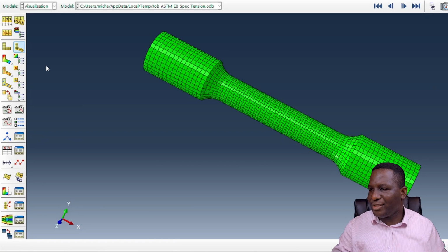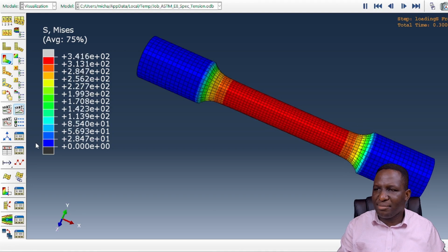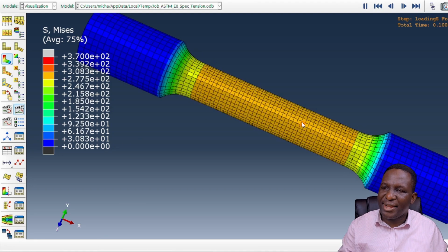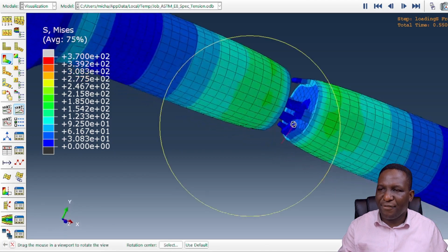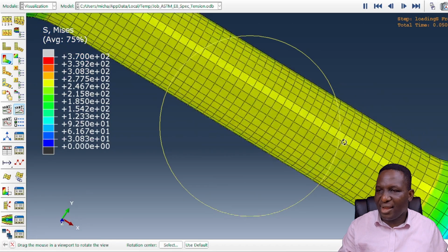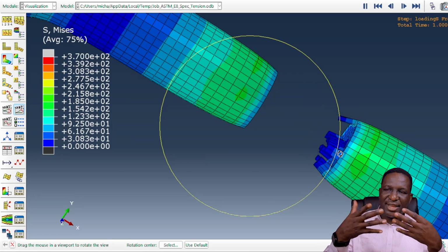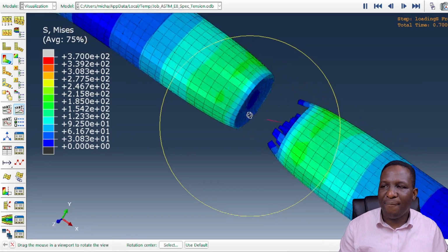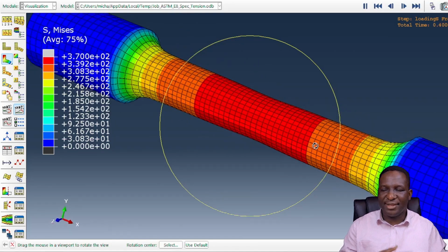So this is sort of what the simulation result will look like. It begins to deform, accumulates, and then we get a plastic deformation right in the gauge section as anticipated. So we get a fracture. Obviously there are tentacles of the sample that are not allowing it to fail, just as you would get in real experiments. We've got tendrils or tentacles as the sample is trying to deform. So there's a clean breakage of the damage, and it's breaking right in the gauge section as expected.